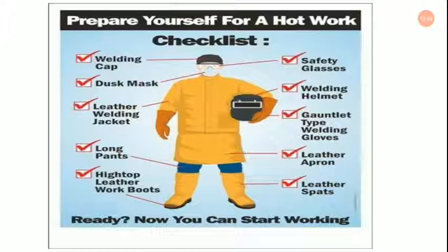Now, there are also some fire hazards. Because of the extreme temperatures associated with any arc welding process, always be aware of fire hazards. The welding arc can reach temperatures of up to 10,000 degrees Fahrenheit, but this heat in itself is not generally a fire hazard. The danger of fire results from the effects of this intense heat upon the work and in the form of sparks and molten metals.